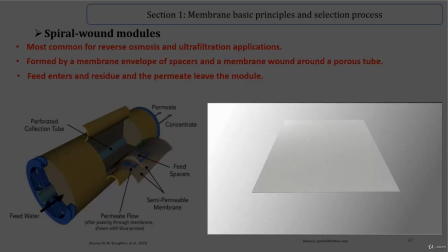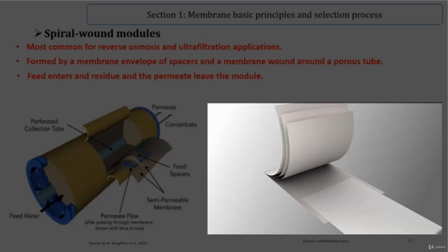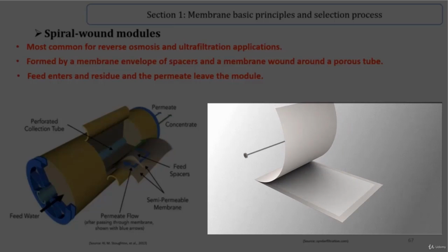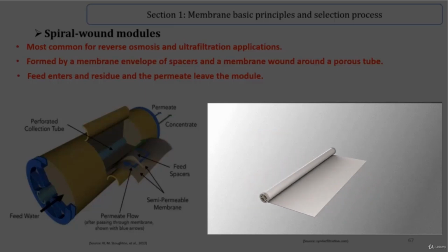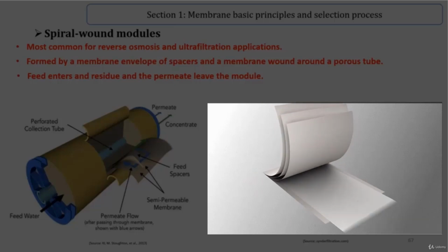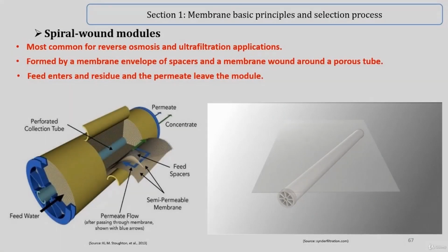Next, the permeate spacer is attached to the permeate tube, and the membrane sandwich prepared earlier is attached to the permeate spacer using glue. The next permeate layer is laid down and sealed with glue, and the whole process is repeated until all of the required permeate spacers have been attached to the membranes. The finished membrane layers then are wrapped around the tube, creating the spiral shape.